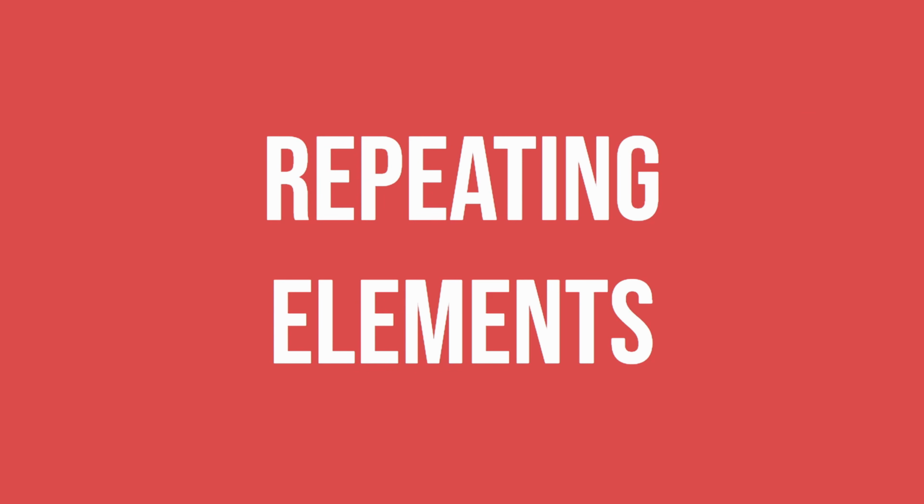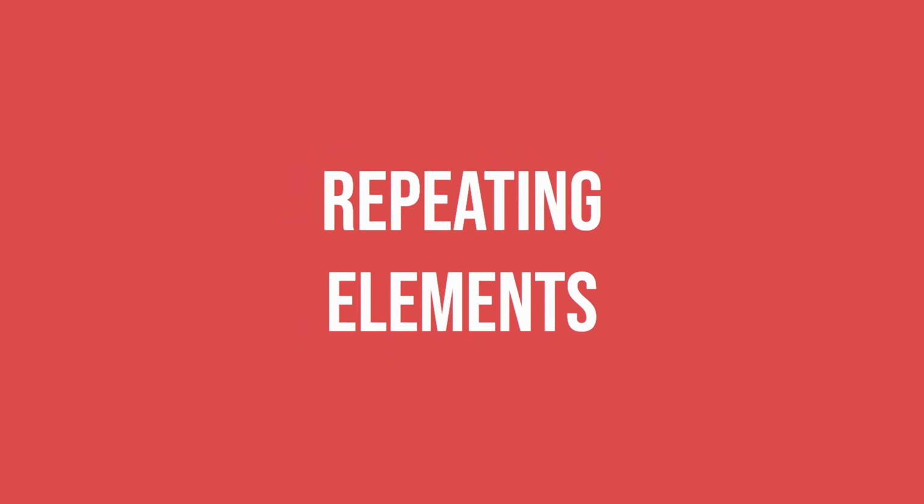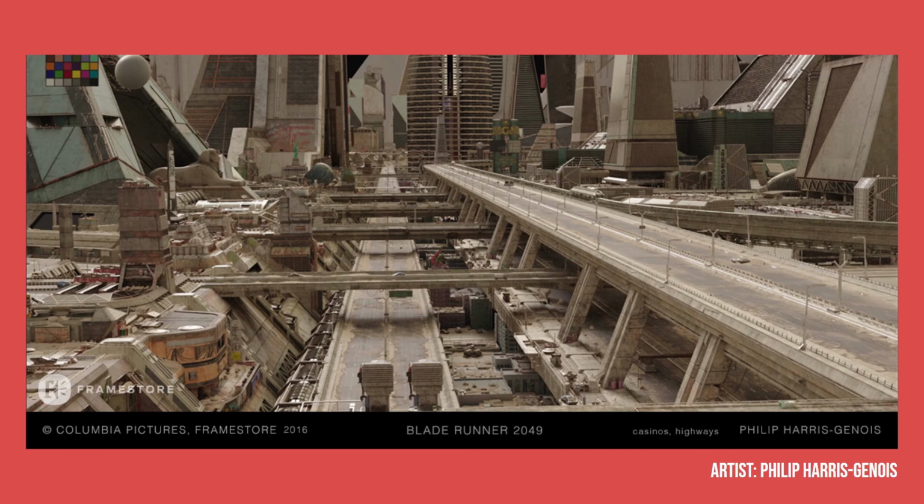There are many ways of creating depth in a 3D workspace. Unlike 2D art, assuming that your objects are scaled appropriately, most of the perspective work is already done for you in 3D software once you find a good camera angle. However, there's still many ways to achieve depth. A pretty simple method to create depth in your environment is to have the same repeating elements get smaller as they get further from the camera. This also works because the repeating elements essentially do the same thing as leading lines, guiding the viewer's eyes, while providing perspective as well.